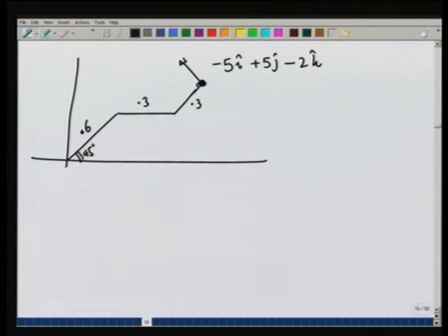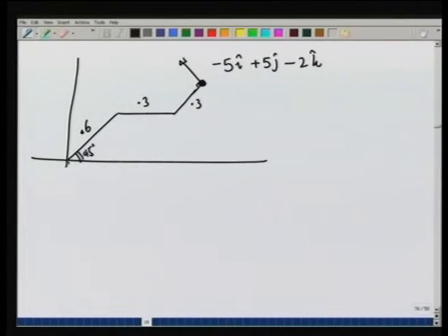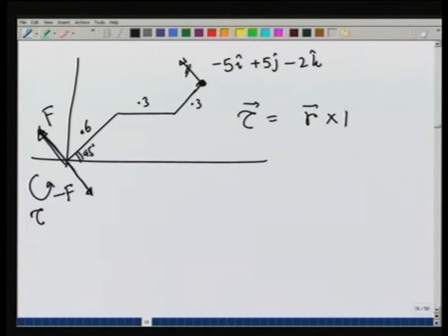The torque of the force is going to be R cross F. Equivalently, I can think of an equal and opposite force being applied here and a force equal to the original force being applied at the bottom. I have done nothing but added a 0 force onto the system. Now, this minus F and the original force therefore create a couple here, which is given by tau, and the force is the original force here. Let us therefore calculate this couple. Either I can calculate the perpendicular distance between the forces, or I can straight away use the formula tau equals R cross F. Let us see what R is going to be in this case.